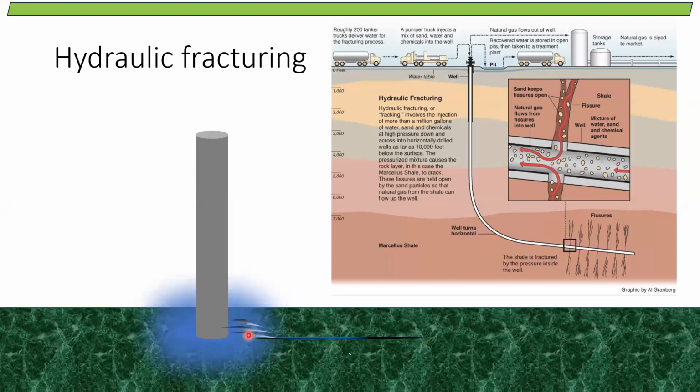After some time of injection, a bigger size fracture will be generated, where the fluid will continuously enter. So all the sand particles and chemicals will enter into your fracture. Once the injection is stopped, that volume of the fracture will be held static, so that the fluids from the reservoir will enter smoothly into the volume, and it will start entering into your wellbore.